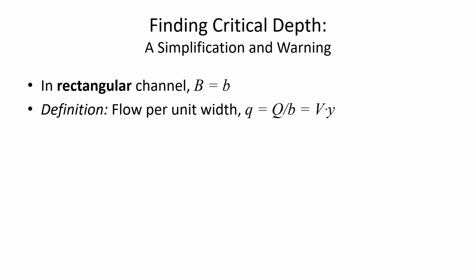Let me just make sure it's 2.25. 10 divided by 4. No, it's 2.5. It'll teach me to do math in my head. 2.5 cubic meters per second per meter. So that's just saying, in a 1 meter width, how much flow is going through that 1 meter section.